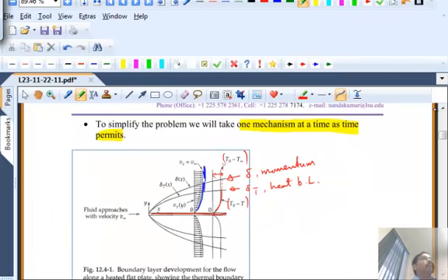So there are two boundary layers, and if you have mass transfer also, there will be a boundary layer corresponding to that. That is the region over which concentration change occurs. So thermal boundary layer, you should think of as the region over which temperature change occurs. Outside of the boundary layer, temperature is constant. Momentum, yeah. Is it always that delta T is smaller than delta? That was the question I was going to ask you. You preempted me. We will think about that. It's a very good question. Will delta T be smaller than delta, larger than delta, equal to delta? What does it depend on? We need to understand that.